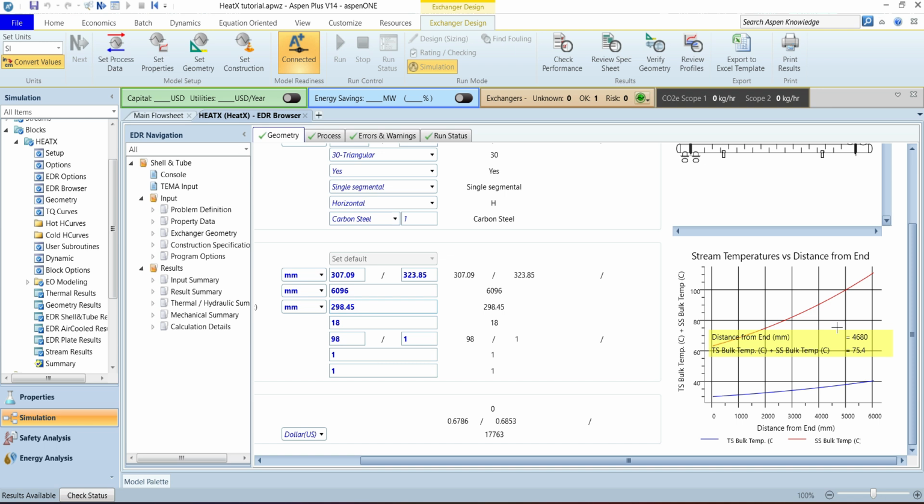The current design fulfills the required service to lower the condensate temperature from its saturation conditions to 65 degrees Celsius. But since the geometrical details of the shell ID and the tube length are not as per common practices, I suggest to slightly work on this and make this exchanger a more feasible fabrication option, where the geometrical information is close to the acceptable limits of industrial practices.